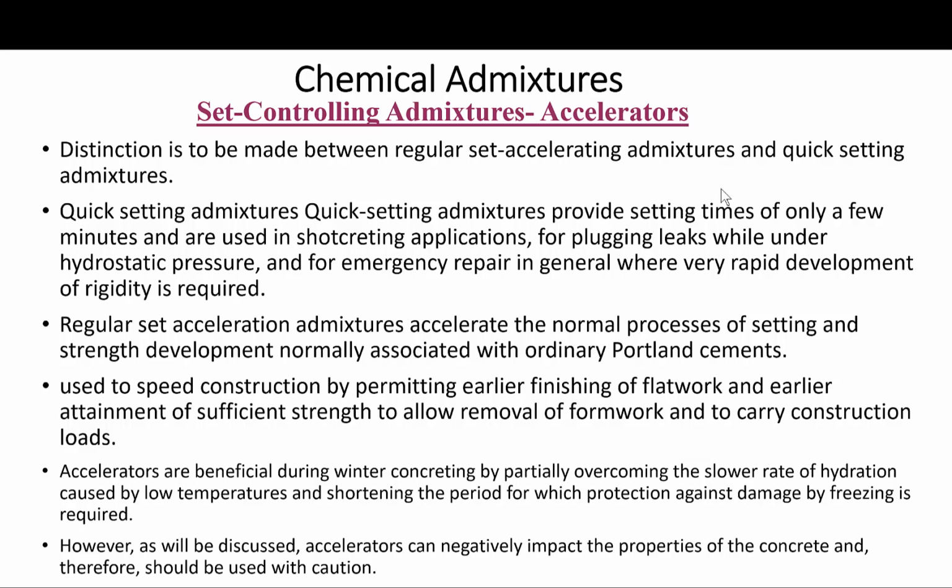Okay, so let's now look at the accelerators. When considering a set accelerating admixture, it is important to distinguish between admixtures that accelerate the normal process of setting and strength development, and the others that provide very rapid setting characteristics not normally associated with ordinary Portland cements.